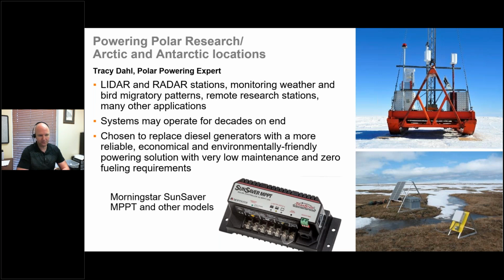One is extreme cold temperatures, and the other is that a lot of these sites are much higher north, to put it lightly, and therefore you will see a very specific application for the Sunsaver PWM, because the solar module is at a very high degree of tilt, because the sun is very low in the sky because of the fact that it's at such a high position on Earth. You've got to change the tilt angle of the PV. So design aspects such as these are obviously unique ones and ones that we work out with a lot of our integrating partners to make sure they have a reliable solution. And this was actually chosen to completely replace diesel generators that were previously being used in these installations.